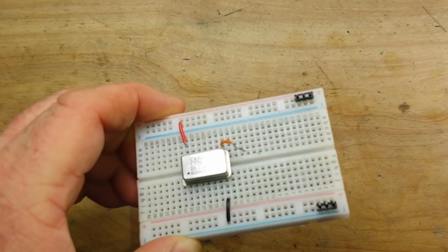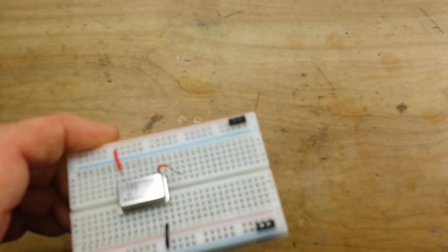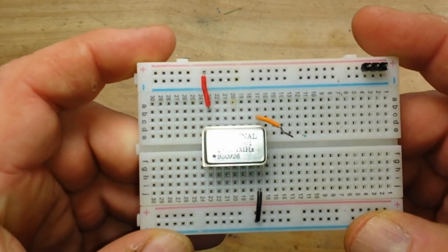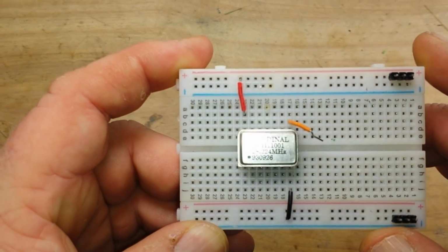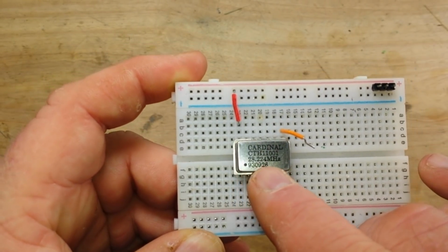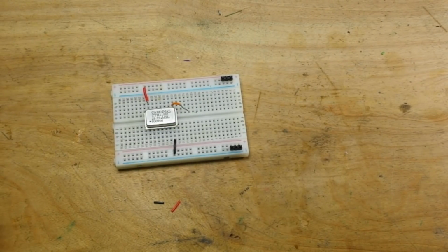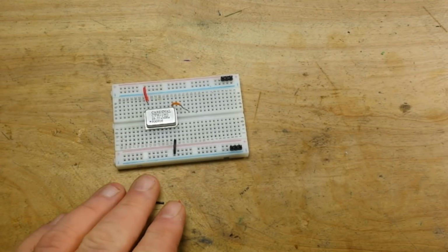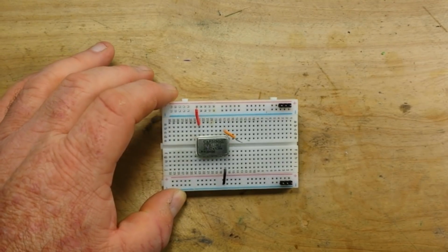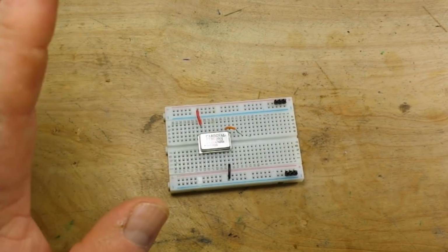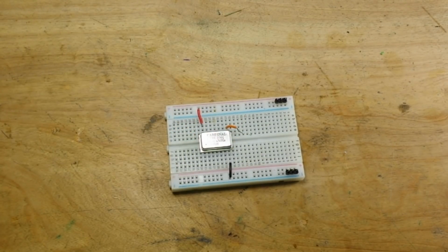Now, there are 14,526,422 different ways to create an oscillator. We're simply going to use this crystal oscillator IC that we have here, and it is at 28.224 megahertz. 28.224 megahertz is in the 10 meter amateur radio band, so what we're doing here is mostly legal. Alright, so we have our oscillator. We're going to put a voltage into the oscillator, and we're going to get out a waveform.